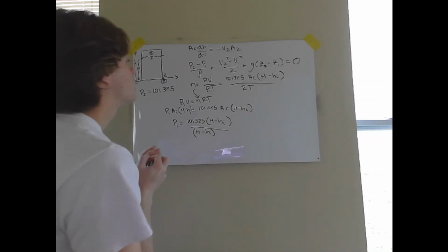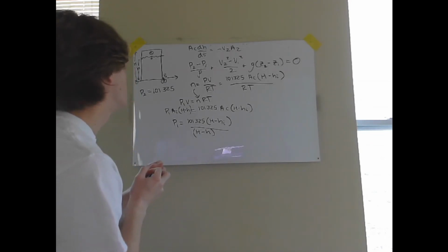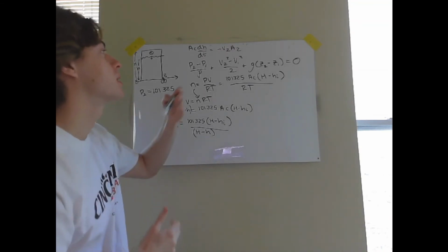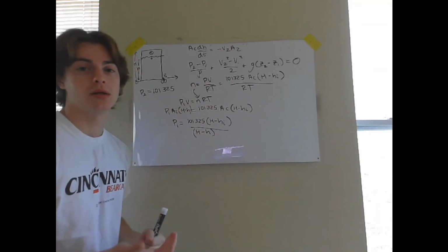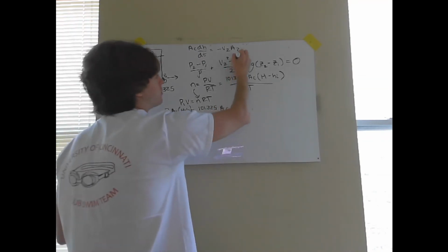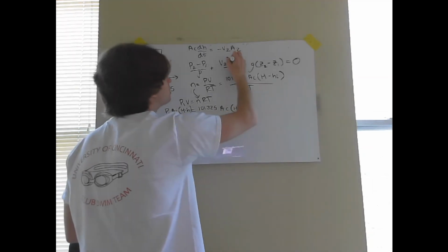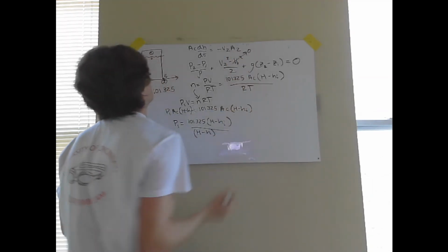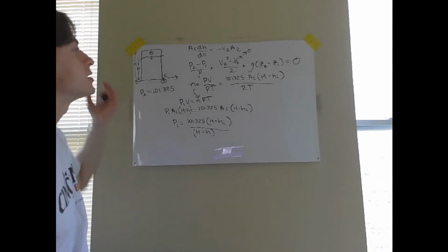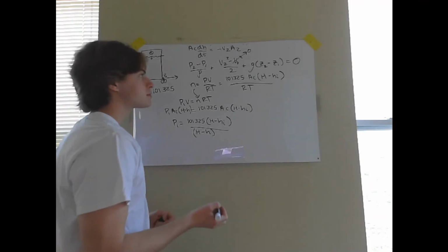Now we can plug these values into our Bernoulli's equation. Before that, I'm going to cover these other two terms like we did with the first scenario. The velocity at point 1, again, is going to be negligible, so this term is going to be 0. We still just have a small hole, so the rate at which this fluid is going down is going to be very small.